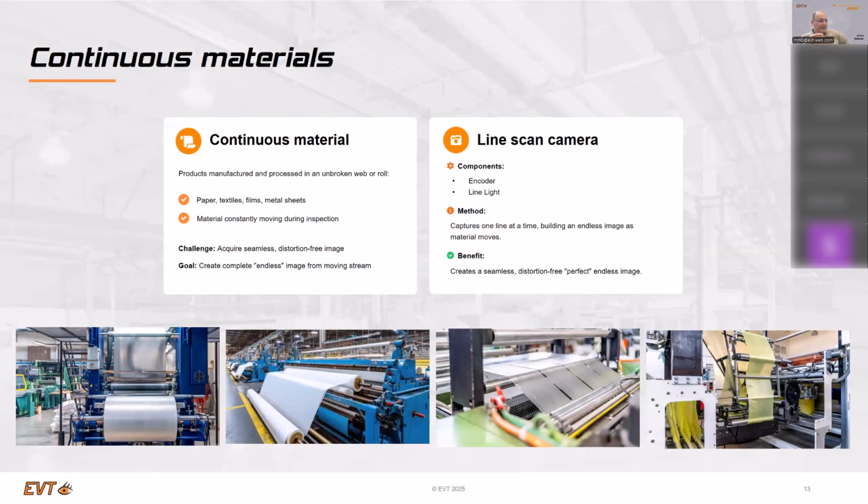If you use the line scan camera, you can work with the production process, with the moving process, for each millimeter or tenth of a millimeter, you can capture a line, and they will be connected together without additional CPU power, so that you have an endless image in your main CPU on which you can operate then.